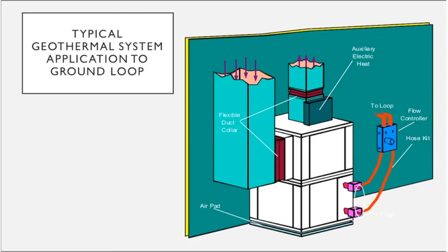Yeah, and once they found it and they shut it off, then it flipped the other way. Yeah. Hey, on my house, for example, I just turned it off at the breaker and never let it run. It never needs to come on. The only reason I'm going to use it is if something were to break down inside the geothermal unit itself, it would be a backup mechanism to run the blower section across that auxiliary coil to get heat into the house until we can fix it the next day.